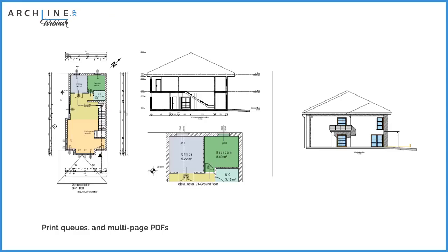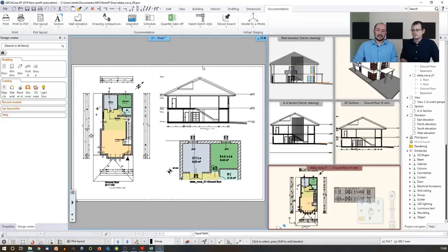That's right. Now let's move on to multi-page PDFs. To create multi-page PDFs, we can stack multiple layouts into the same content using the print queue. But before we do that, let's create another page onto this layout, and we will assemble them. So we will go with this one, and we will prepare a new plot layout using this plot layout tool again, and prepare plot layout.